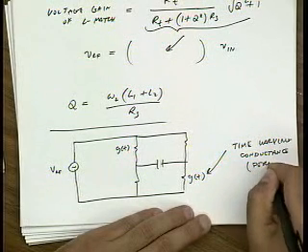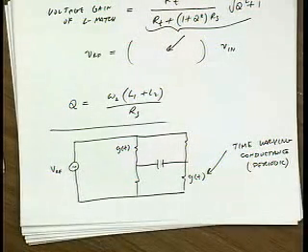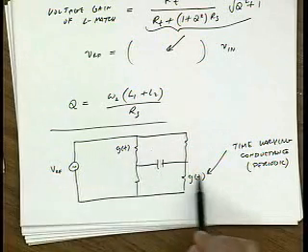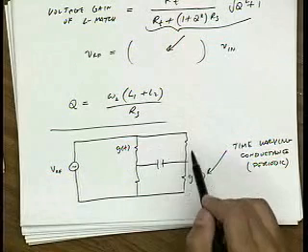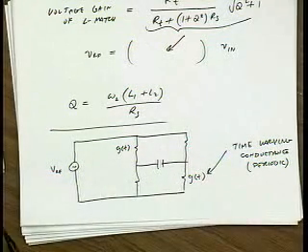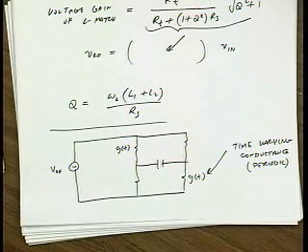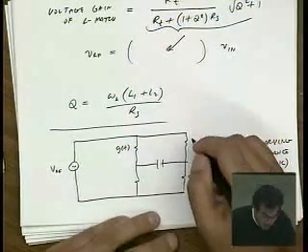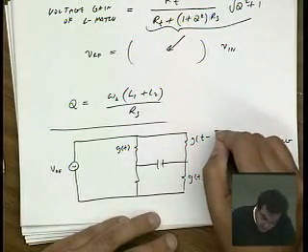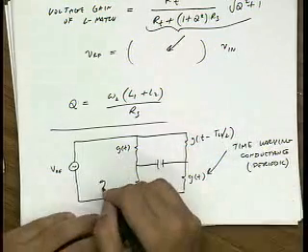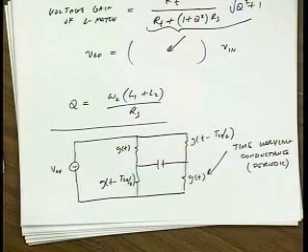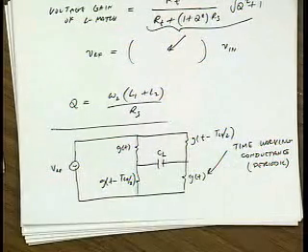which is of course periodic. Okay? So if the conductance of this resistor is G of T, remember this one is driven by LO and this one's driven by LO bar. What's the conductance of this device and this device? Exactly. It should be the same, just a delayed version, or a time-advanced version, because it's periodic, it's just the same conductance time-shifted. Okay? So this is the equivalent circuit, and this is basically my load capacitance.